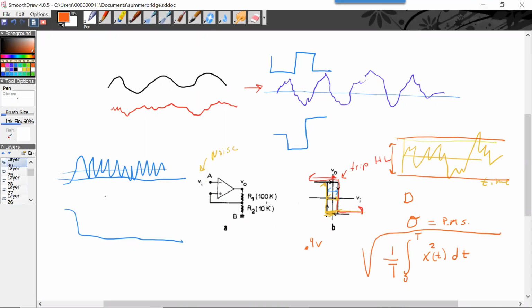Now, the important thing about stochastic resonance is when you're detecting it, you actually put the signal you're trying to detect here. All right. Now, it's important that that peak to peak fits within here as well, because if this is really large, it'll act like a non-inverting Schmitt trigger, and you're not really getting stochastic resonance.